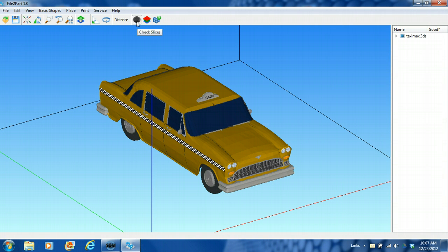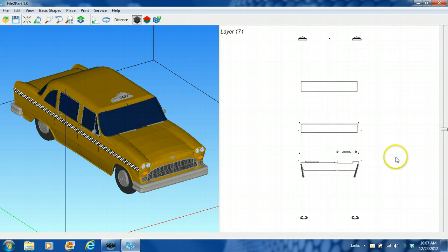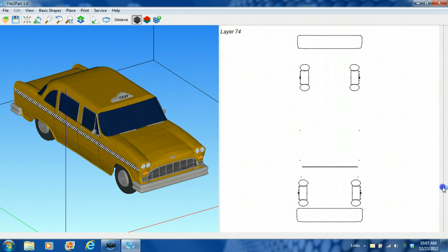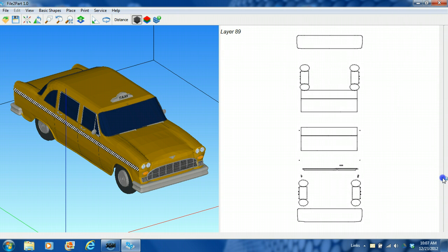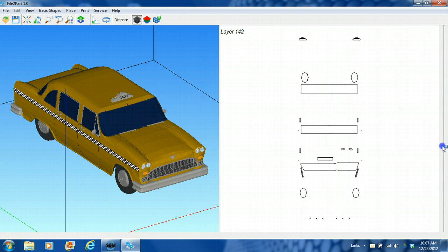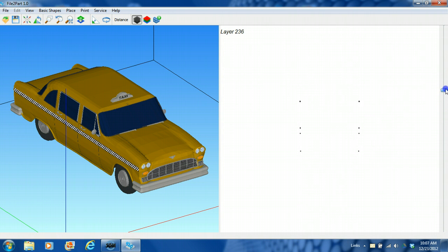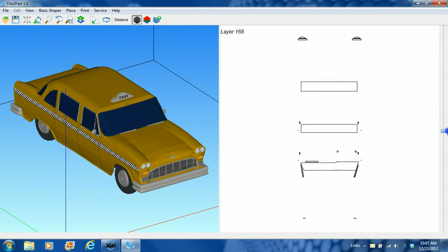Now, check the slices feature. It's a very simple and primitive algorithm for a quick scan. The dark area shows us where material is going to be deposited during the build. As you can see, in some areas, very little material is deposited right here. So probably this part won't have structural integrity and needs some editing and file fixing. I'll show it in the next video.